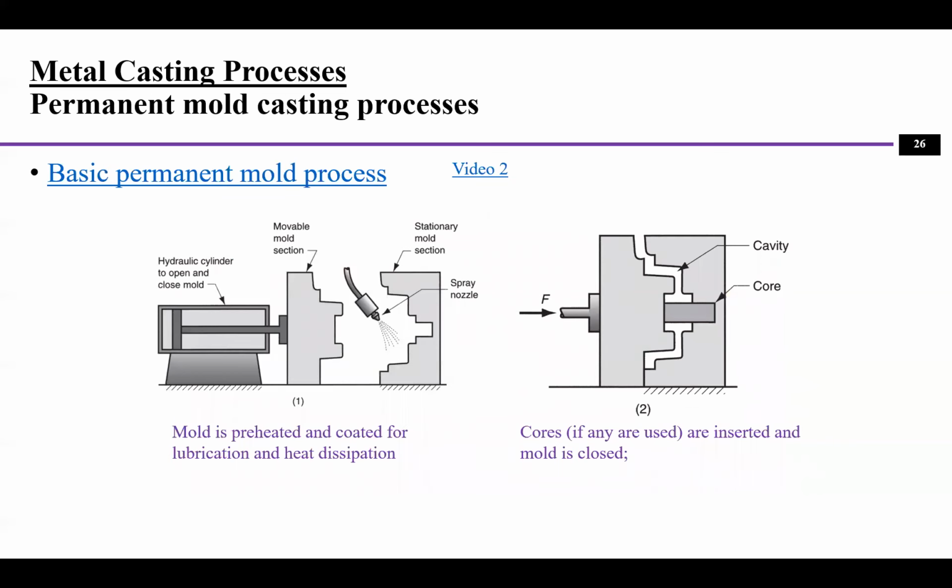And so the problem with sand casting and also the lost foam process is that every time we need to make a new mold. Think about the sand, right? You get a part, you finish, and then you have to break the mold, because otherwise how can you get the part out? And that is really a waste of time unless you are doing a lot of customization, right? It's not a large high volume production.